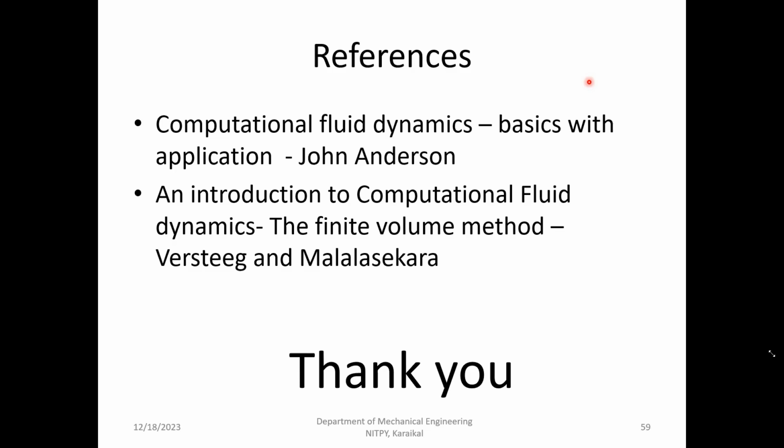So when you're going to take an initial heat exchanger, take a standard model available in the literature, and then check whether you're getting the same values without nanofluids or with pure fluids. Then we can be sure when to stop the iterations. Otherwise, we'll not know when to stop. So generally, you can allow the iterations to run, maybe save it every 1,000 or 2,000, and then compare the results, whether it is improving or not. If it is not improving, you can take that itself. If it is improving, you can wait till it reaches what is reported in the literature.